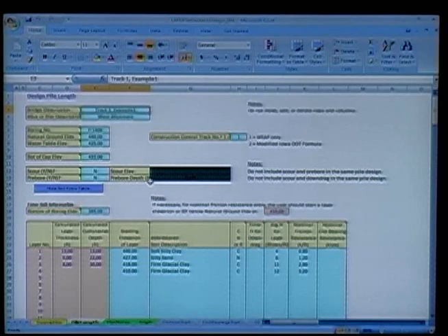So once you get through these upper layers of input in the blue cells, you'll jump down here and put the bottom of boring elevation. I use this basically if your pile ends up being longer than your boring, you can decide whether you're worried or not. At the DOT, we found out sometimes people go 20 feet, their pile's 20 feet below the bottom of the boring.